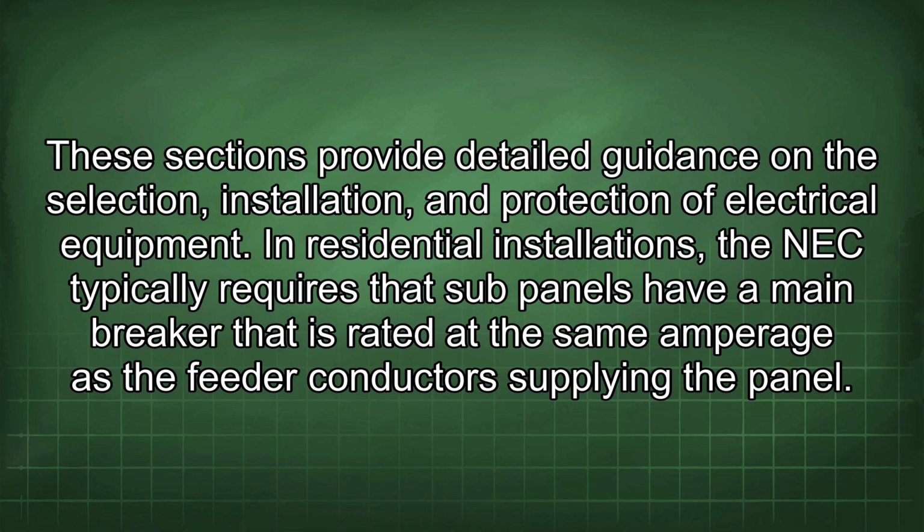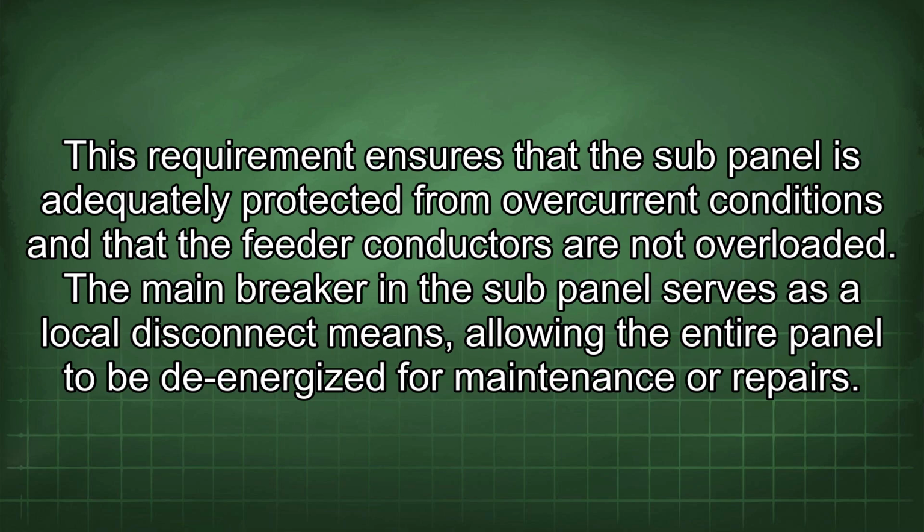In residential installations, the NEC typically requires that sub-panels have a main breaker that is rated at the same amperage as the feeder conductors supplying the panel. This requirement ensures that the sub-panel is adequately protected from overcurrent conditions and that the feeder conductors are not overloaded. The main breaker in the sub-panel serves as a local disconnect means, allowing the entire panel to be de-energized for